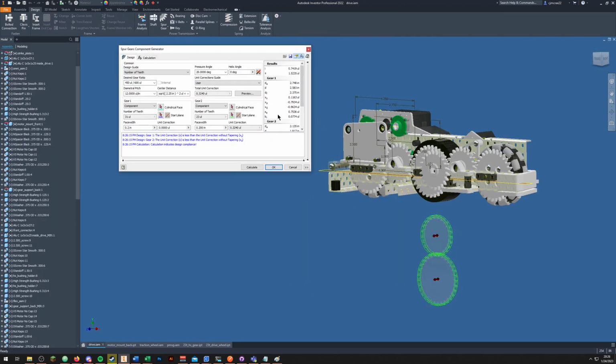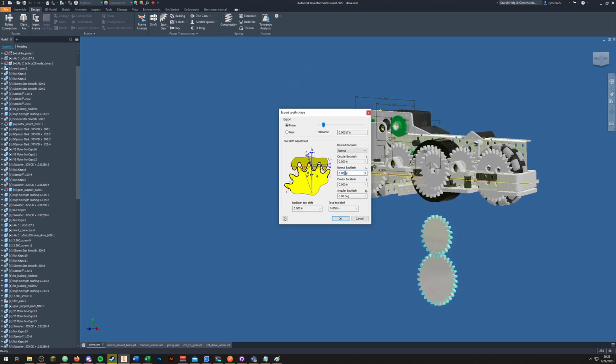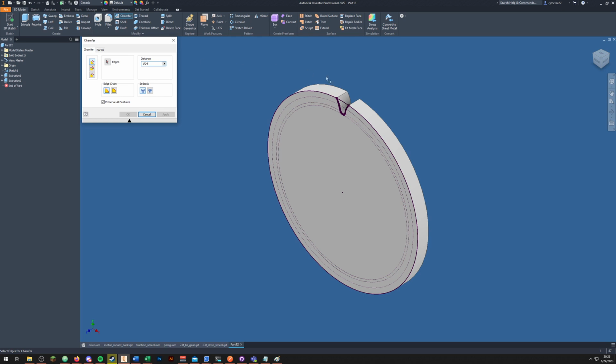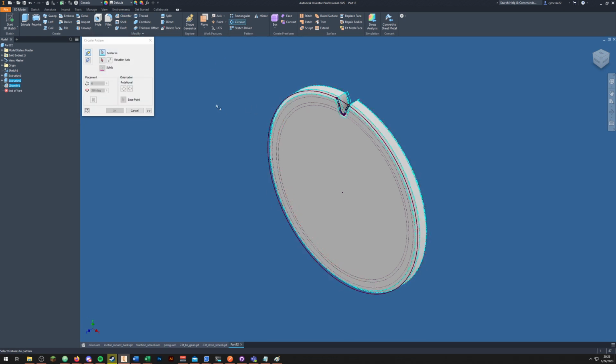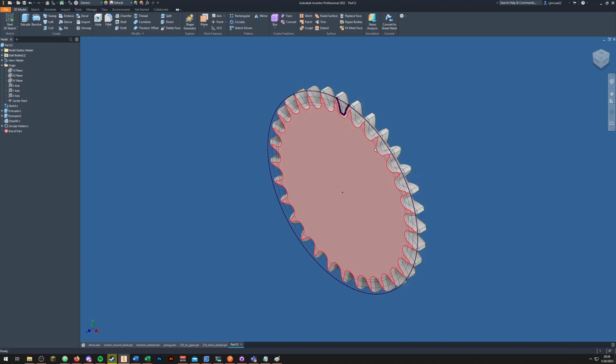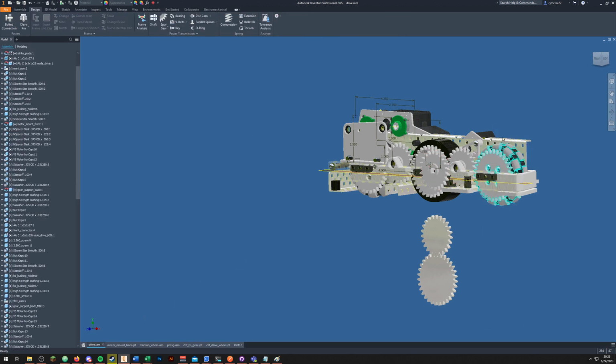So export tooth, we're going to do it just one more time. Yeah, this looks bigger, so okay. Third time's the charm. All the way through. Chamfer, 1/24th. Circular pattern. Around Z, 31. Let it think. That looks much better. Disable this sketch. Then we can come back in here.